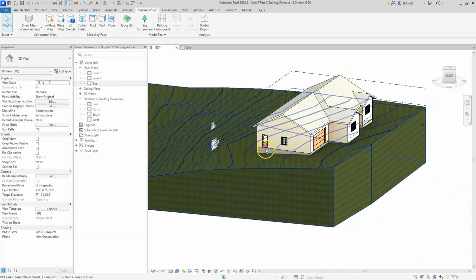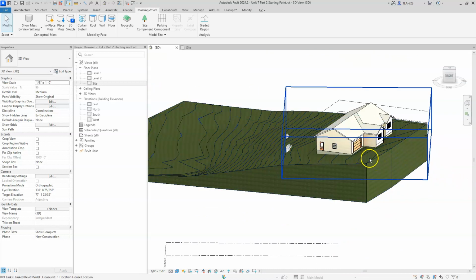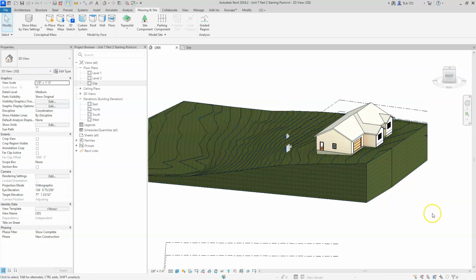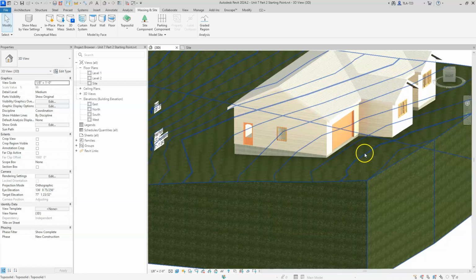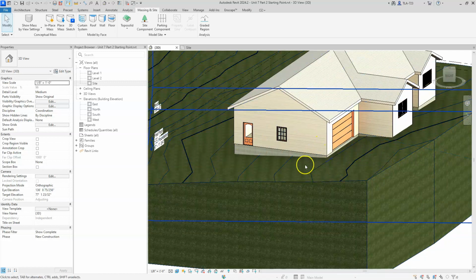So for example, if you had a gravel driveway that's coming across a large portion of land, and it mostly just follows the natural contour of the ground, painting on a gravel driveway is a whole lot easier than modeling a gravel driveway with a whole separate component. Another good example of that is a sidewalk. A perhaps even better example would be a rock bed. You know how a lot of people will build a rock boundary around their house. They don't want to mow right up to their foundation, so they're just going to do a squiggly border around their house and then fill that part up to the foundation with rock or some other material like mulch, perhaps. But in a lot of cases, that is going to follow the natural contour. So it doesn't really always make sense to create a whole separate thing.